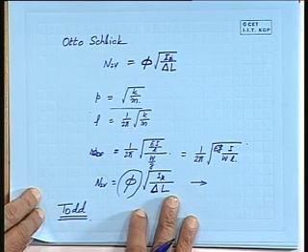And Todd realized this, that when the ship is in a floating condition and vibrates, the water in which it is floating is a real fluid and it sticks to the hull, and therefore when the to and fro motion is taking place, the water also moves along with it. So there is a virtual increase in the weight of the vessel at the time of vibration, which Otto Schlick was not taking into account, and he was getting a higher frequency here.